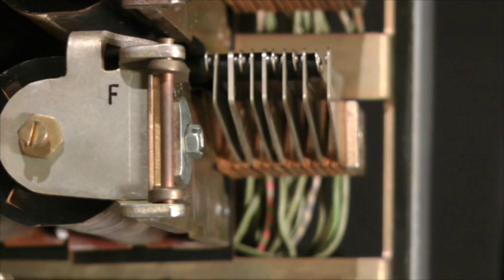B operated transfers the connectivity of the transmission path wipers through the line finder from the lower bank tier tip and ring wipers to the middle bank tier tip 1 and ring 1 wipers. It also closes the operating path for the full and direct operation of the F relay via the F relay's secondary winding.